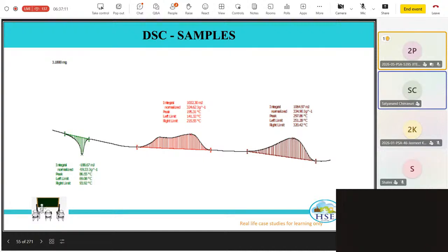It will run on its own by having incremental temperature rise, based on the self heat that is liberated from within the mass. It will be absorbed by the process mass, and it will start having a temperature rise, and ultimately it will go to the temperature wherein it will run away. So TMR 24 is the temperature value at which you will still have 24 hours of time under perfect adiabatic conditions. And TMR 8 means you have only 8 hours of time.